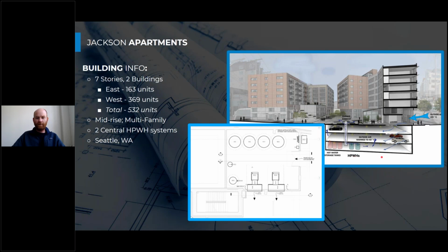And this is true for most maritime climates. It's not just Seattle. Portland, this will probably work well too. I know that it gets a little bit cooler there in the winter because you're not as close to the sound or the ocean. But this can be a really great strategy, especially because a lot of these multifamily buildings already have a parking garage, and there's typically empty corners, often low down, that we can use to put this heat pump water heating equipment.